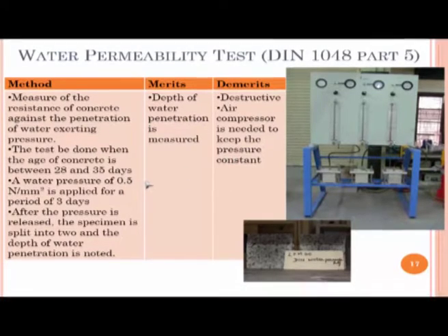So the water penetration test as per the German standard DIN is a very common test. Today, in many specifications for concrete prescribed for metro construction, for instance, or even bridge construction, a lot of the consultants prescribe the water penetration test for concrete supplied to the site. That means all the concrete supplied to the site must not only meet strength requirements, it must also meet water penetration test requirements.